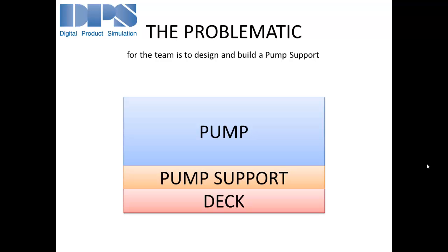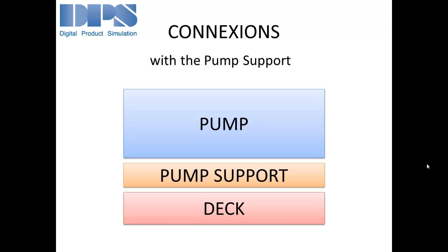All the constraints will come from the workers: what they can build, what they cannot build. What will be the connections with the pump support? First, between the pump and the support, we will have bolting connections. Between the pump support and the deck, we will have welding connections.